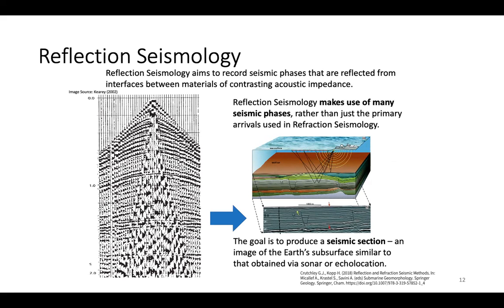Each of those little wiggly lines which go down in time effectively corresponds to one hydrophone that's been listening to reflections coming back. And you can see that underneath the surface and the direct arrival, in this case through the water, we see these little parabola-like things. Now these would correspond to individual reflectors underneath.